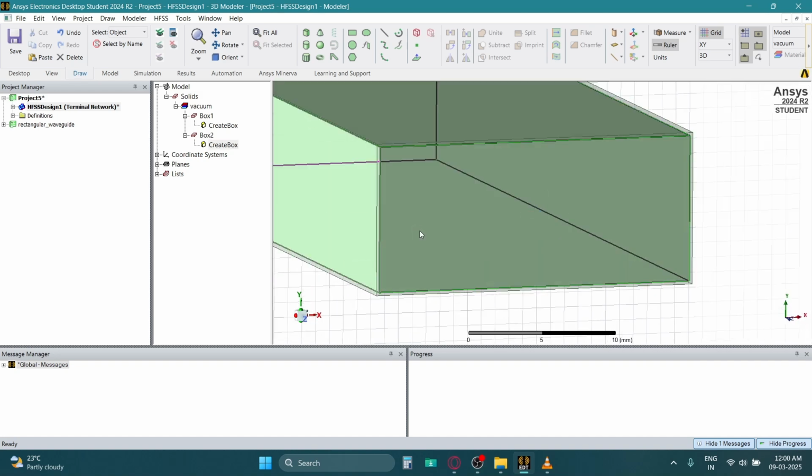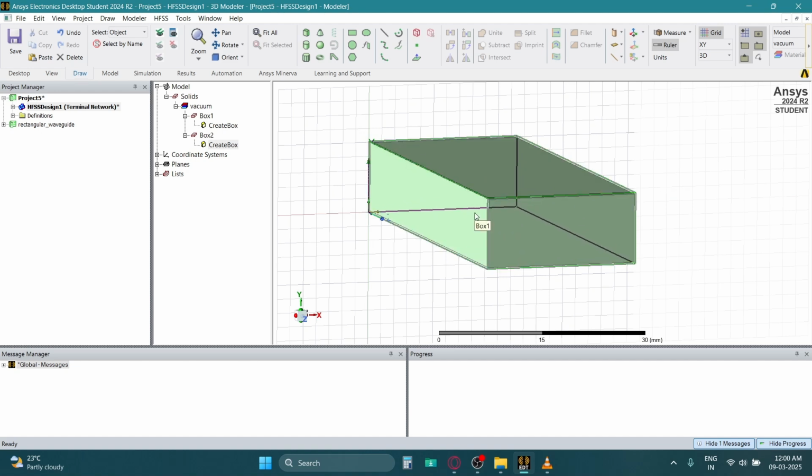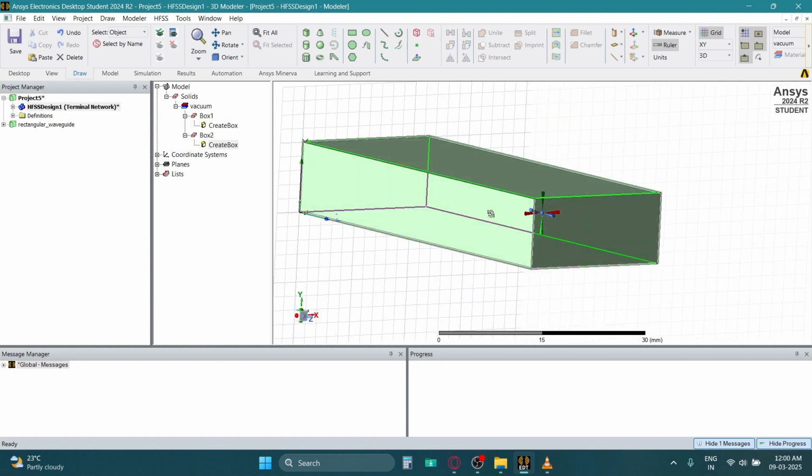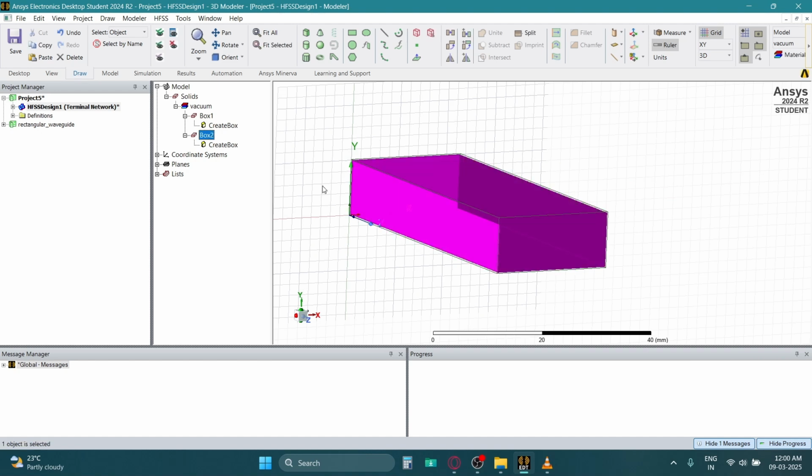That's all. Now what we'll have to do is, both of these are solid boxes, so we'll have to actually subtract the inside box from the outside box. That's very easy to do, but right before we do that, I will copy this box and paste it again. So I just did Control C and Control V. So now we have two of these boxes, and the reason for doing this will be quite evident soon. I'll just leave that there.